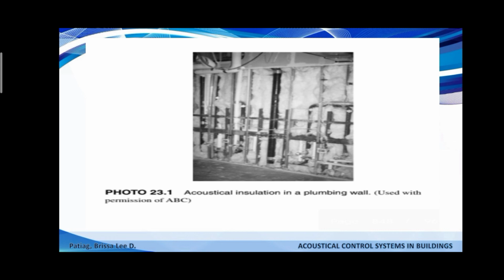Doors will also typically represent the weakness in the good wall. So, insulation ratings of the solid core doors may vary from STC 15 for swinging door with clearance all around to STC 27 for the same door completely sealed by gaskets or weather stripping all around.